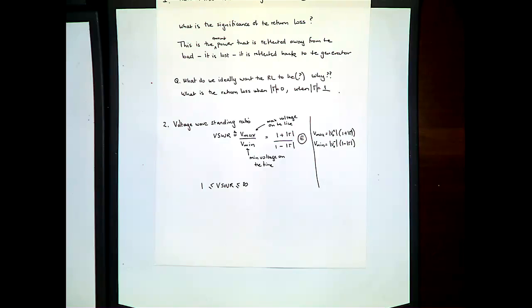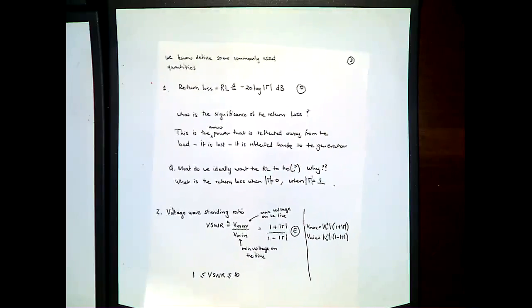And the other reason why it's important is that sometimes you might be connecting logic gates, or something else which is sensitive to that particular transmission line. So it also indicates to you what the maximum voltage could be, right? Because if you know roughly the ratio of the input to output voltage, and you can make an approximation that the transmission line is roughly lossless, you can say, well, I'm putting in X volts, so this is the ratio that I would expect. So this is the maximum voltage I would expect on this particular transmission line. Okay, excellent. All right, so we're all excited now.